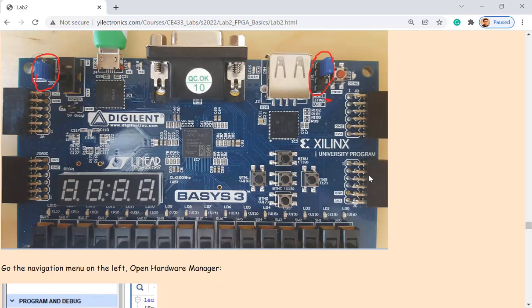So you think your bin file worked, but actually it's the code from 3 years ago that somebody else programmed into the memory. I didn't clean it up or reprogram it since then. So the only way you can demonstrate that your program in the bin file works is to use a different program. Just use the OR gate instead of the AND gate here.